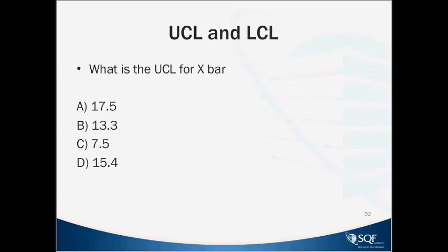It tells you a story about the process, and then if you react quickly, you should be able to drive variation out of that. So, thank you, Christy. Okay, so your quick calculation, you should have got a value of 17.5 for the upper control limit for X bar if you did that correctly.